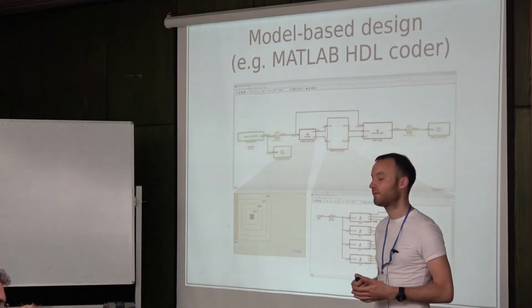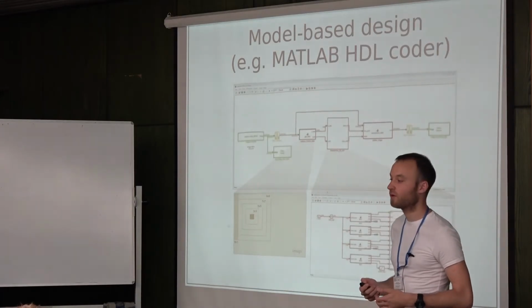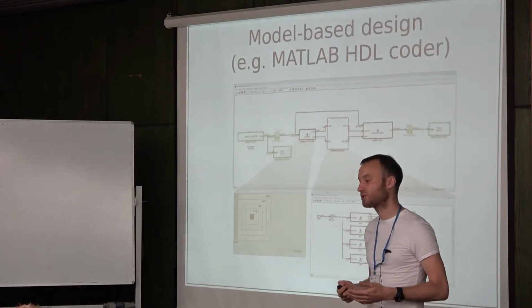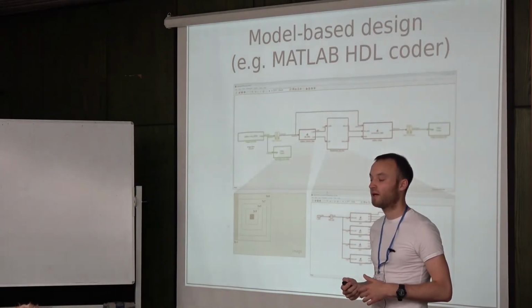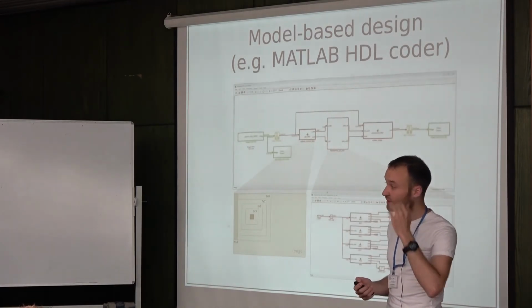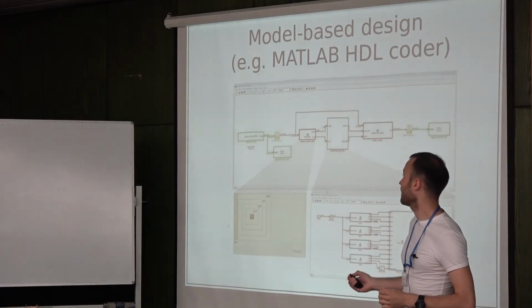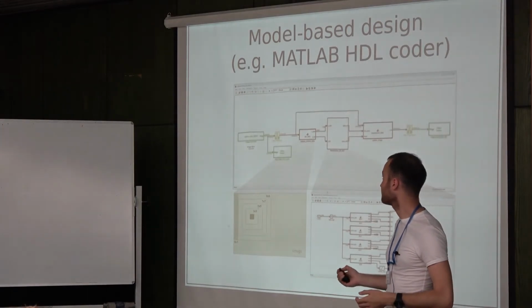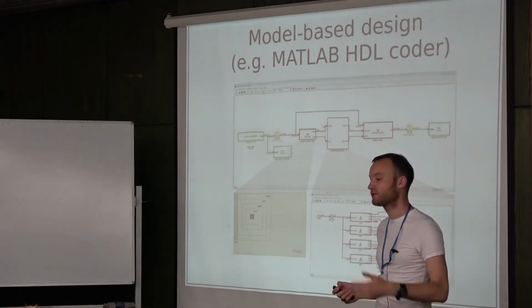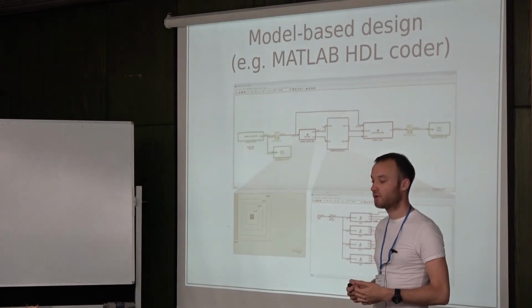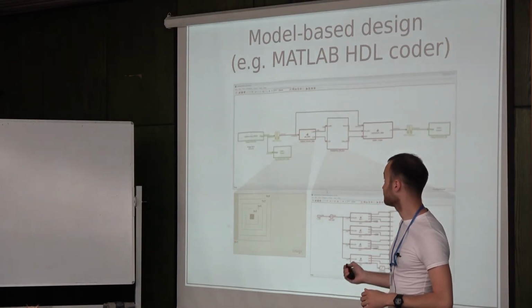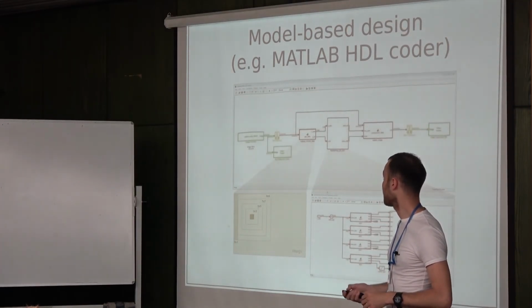So you will find something like a fast Fourier transform block, maybe a matrix vector multiplication block, some FIR, IIR filters. So you connect them, and you can synthesize your circuit and deploy your algorithm on hardware right from the Simulink environment.